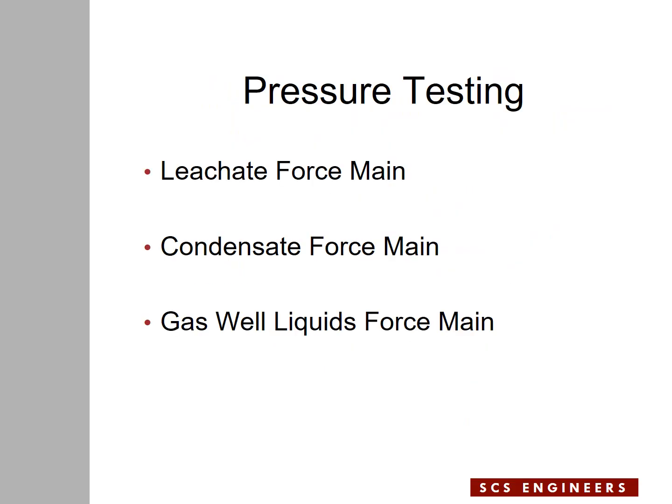Pressure testing is normally carried out on solid HDPE pipes that are used for high pressure liquids passing through them, which could be a leachate force main, condensate force main, and gas well liquids force main, which could be a smaller force main extending from a gas well to a larger force main to a storage tank.